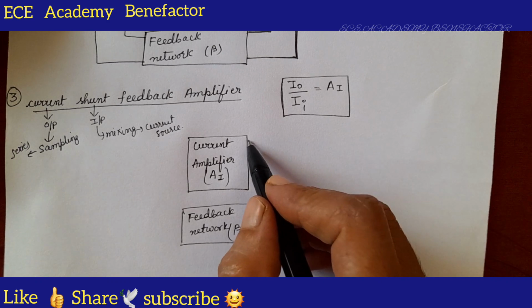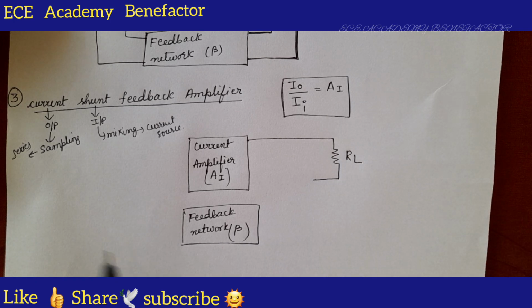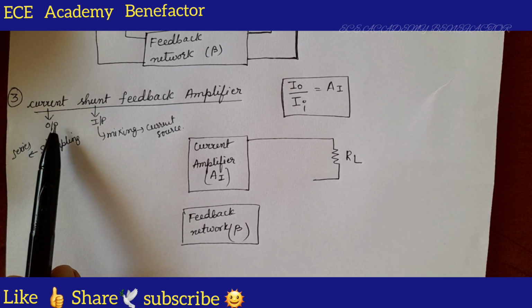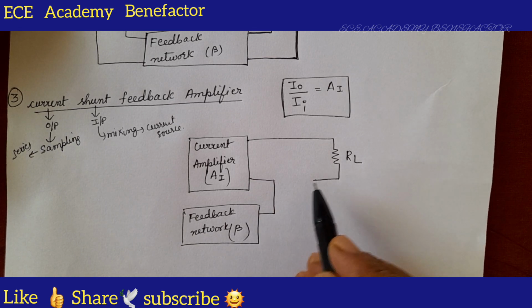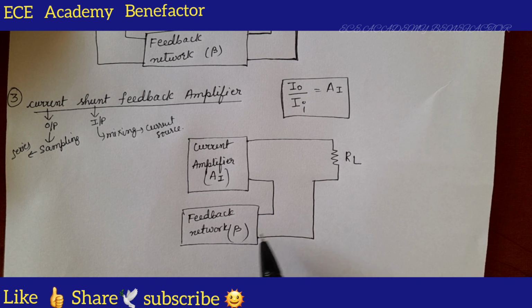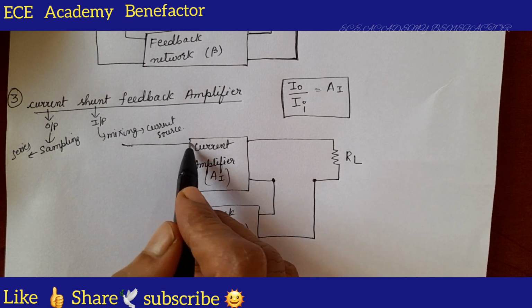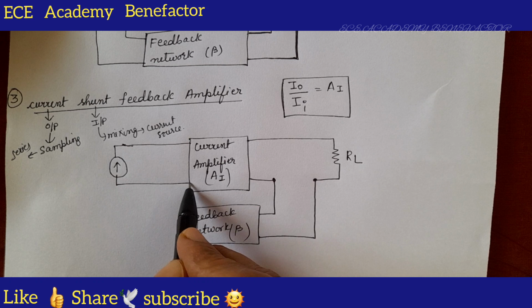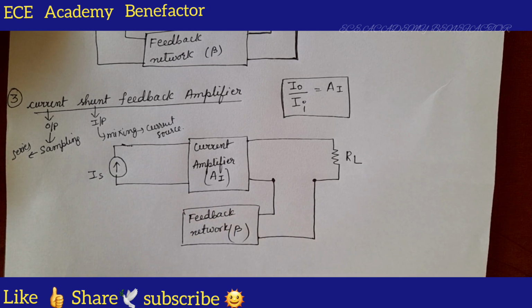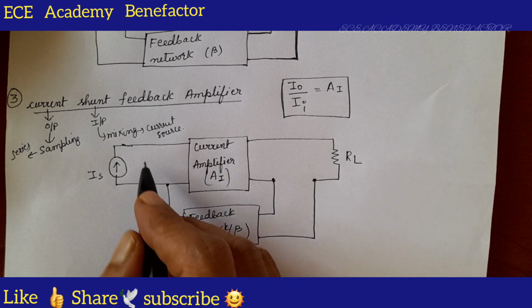At the output side, we need a load resistor RL. How is the connection at the output side? Current sampling. Current sampling means series connection. So we have to connect it in series like this. So this is series connection. And at the input side, shunt connection. So what type of source do we need to place? A current source, IS. And how are the connections at the input side? Shunt connections. So like this we need to do the connection.